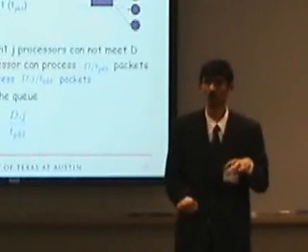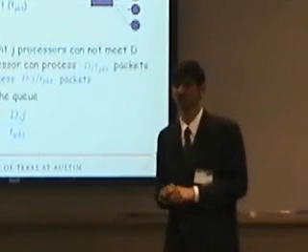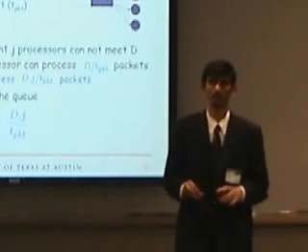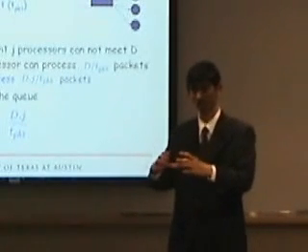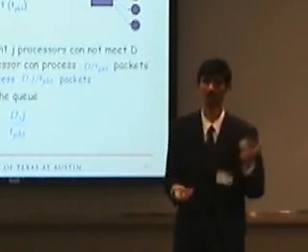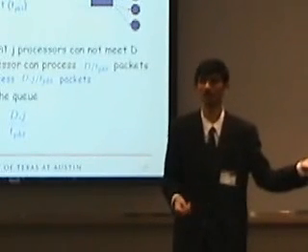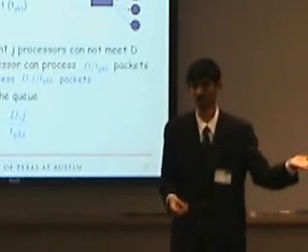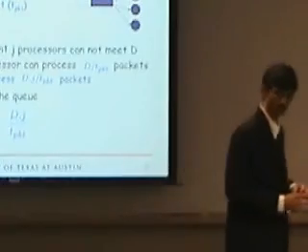How large is the instruction store? It's 4K instructions, and the instruction store itself is on the processor on chip, but the code that you're trying to write onto the chip is on the SRAM off chip. Is that loaded on demand, or is it preloaded before you start executing? So in the mapping phase, we are loading the code, and then we are starting to run the system. But when we are adapting, that's when we are writing the code again.